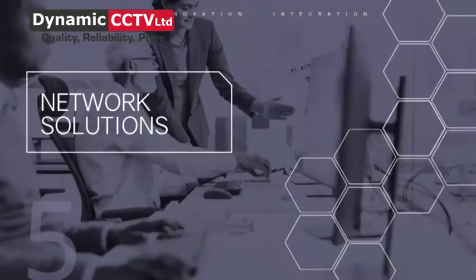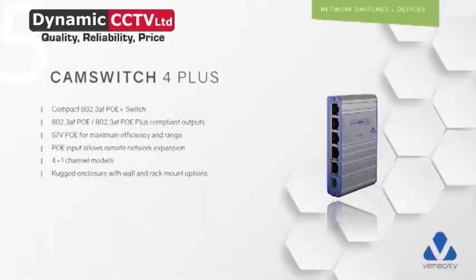So that brings us to our network solutions. The first thing we're going to look at is the CAMSwitch 4 Plus. CAMSwitch 4 Plus is an 802.3at compatible device, as you can see on the screen. It's what we call a 4-in-1. Okay, so 4 PoE ports, 1 non-PoE port, one back into your network, and you still have your 4 PoEs.